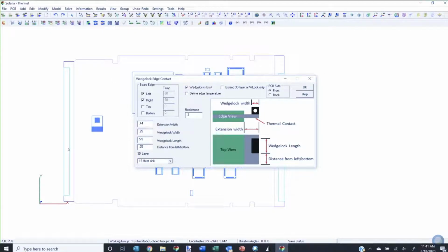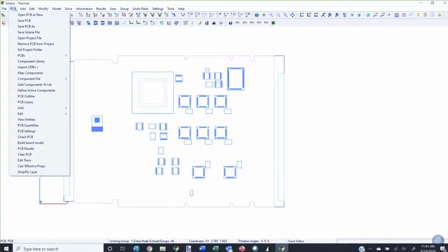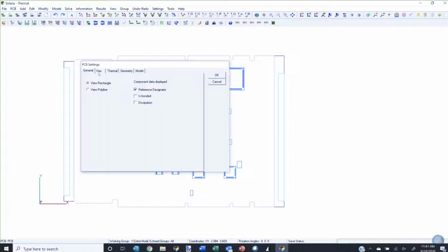So when I disable defining the edge temperatures, it'll automatically create the interface elements. And instead of making boundary nodes, it's going to create slave IntelliMesh surfaces. And those are the surfaces that I'll want to mate with the ones in the box I just created.